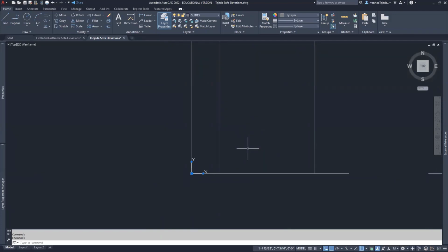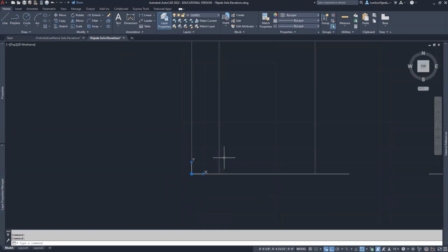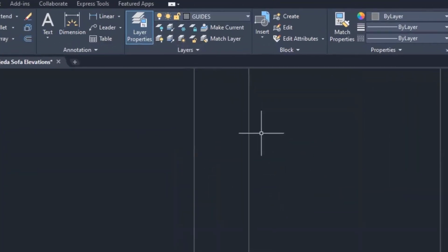What I'd like to do is place it on the correct layer. Now, what is that correct layer going to be? In my example here, I placed that object. You can see if I just hover over it, it's on layer number 2, which is medium. Why medium? Because it's neither in the foreground nor the background, somewhere in the middle. And these are the legs underneath the sofa that I don't quite see. It makes sense for me to put it on this layer. So here's what I'm going to do. I'm going to go ahead and make that layer my current layer so I can draw on it. I'll come up here, go to medium like this.